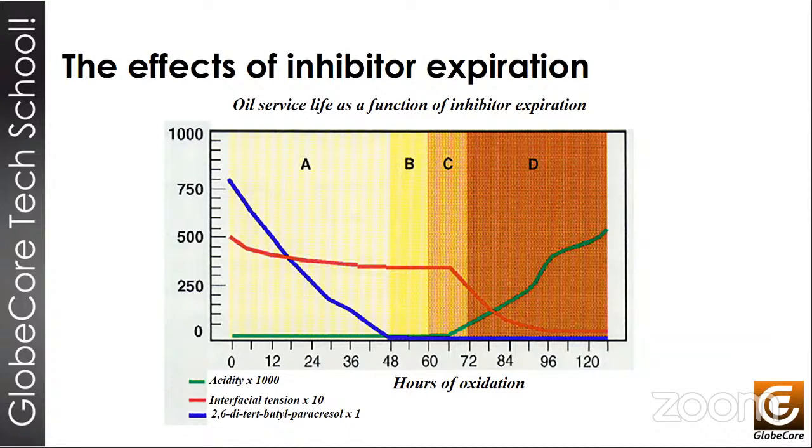And then something important happens, and you will see this in this graph when things start going bad rapidly, okay? And this means that the transformer can no longer absorb these contaminants. It's reached its saturation limit. And so these products remain in the oil. And suddenly we have a serious loss in performance characteristics and in the deterioration of the chemical properties of the oil. And as we can see from this graph, the problem did not occur when the color changed or when acidity increased or when interfacial tension dropped. The problem starts when the oxidation inhibitor is depleted. So if we stay on top of that, if we keep track of the oxidation inhibitor content, we can identify any problems early, and we can actually prevent this problem from ever happening, okay? Next slide, please.